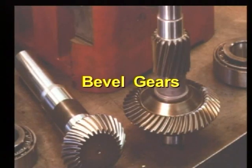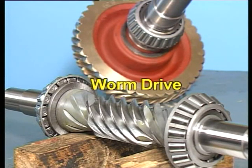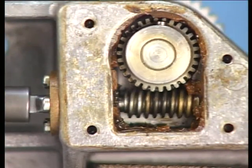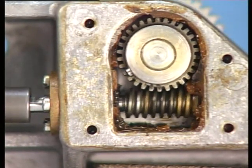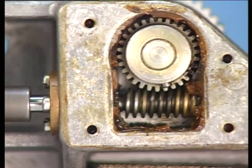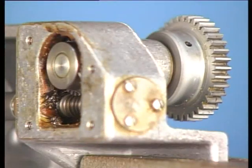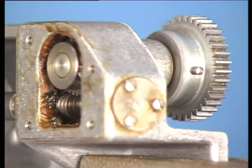One method used to create an angle drive is through gears called bevel gears. A very popular angle drive, and one which you will see again in this series, is the worm and wheel type, often simply called worm drives. The action of the worm drive can be seen clearly here in this model. A screw thread, called the worm shaft, acts as the input. Motion via the screw action is transmitted into the worm gear. The output shaft, being the axis of the worm gear, provides the 90-degree change in the power flow direction.